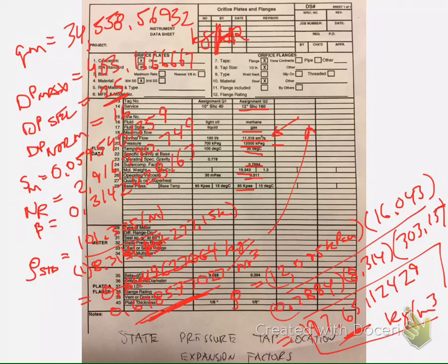And now it's asking me for my expansion coefficient, and they use stainless steel up here again. So that was 1.1 times 10 to the negative fifth. And our piping is carbon steel, which I don't think it's showing here, but the one for carbon steel that we used in the last example as well is 1.6 times 10 to the negative fifth.